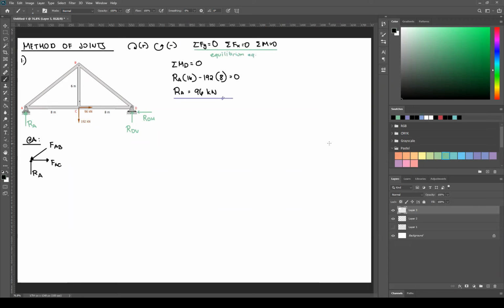Okay, so now you have a choice. This is just a concurrent force system, as mentioned earlier. They all intersect at a point. The only equations you can use for concurrent force systems are Fx and Fy equals 0. So you can start with either, and you'll get the answer eventually. But if you want to make your solution shorter, you can analyze first which equation will give you an answer immediately. So let's say I did summation of forces x first.